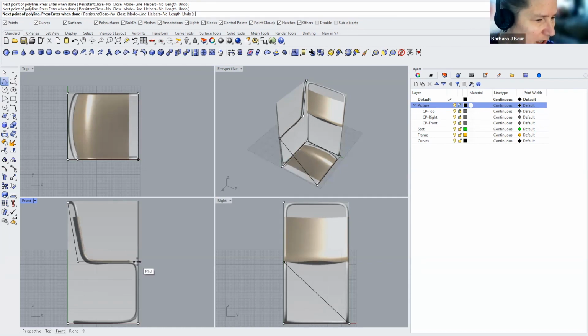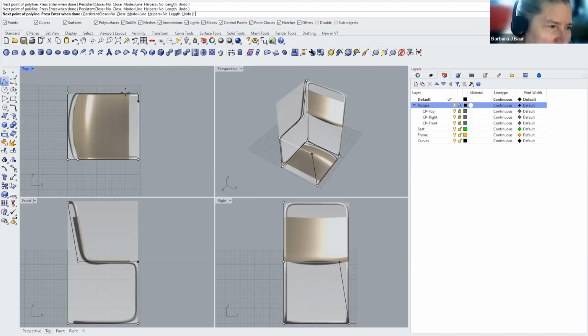So I'm going to take off grid snap too. I'm going to hold down Control before I click. Click. Now you can see in the perspective viewport what I can do with this. I can stop anywhere on that line, and it'll be directly opposite of that point in the front of the chair on the right-hand side of the chair.